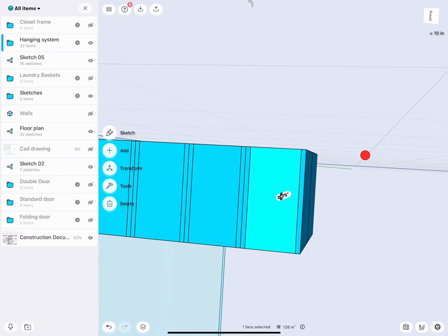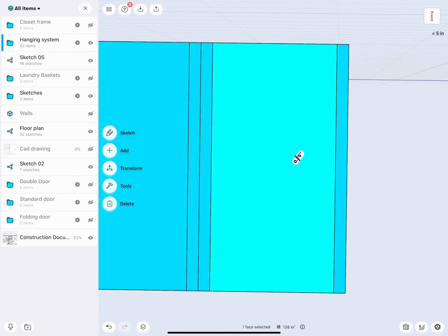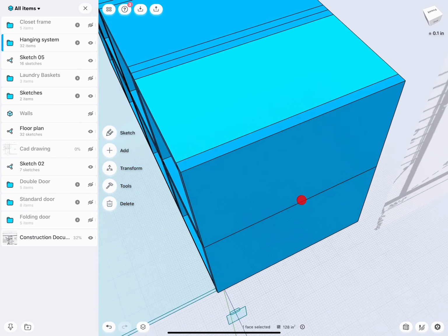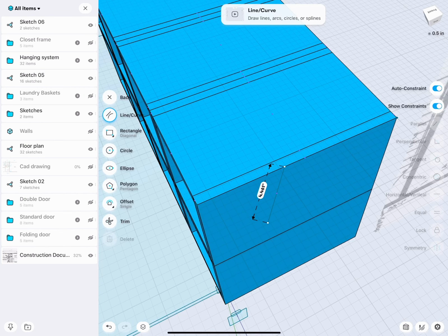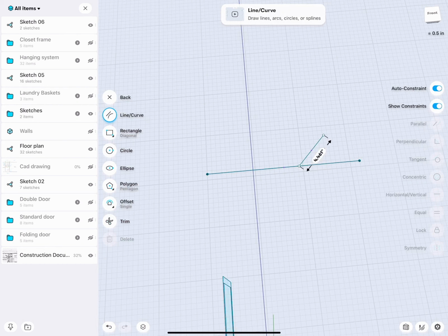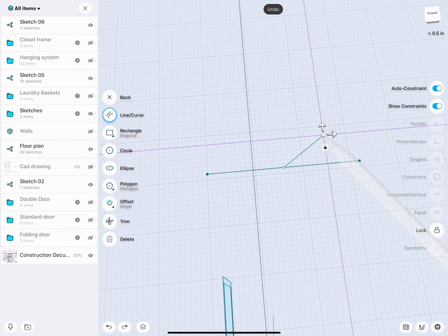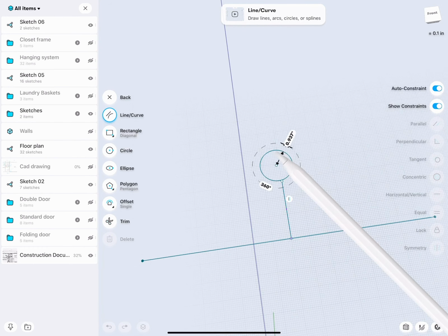I could select this side because I would like, obviously, the rod that's on top to be centered so it does not hang down rotated. So I can select this side with a finger now, double tap. So check this out. I will draw just somewhere a line and touch this edge, and then it will project this edge into a sketch. There I have a center point, or sorry, a midpoint. This I will make horizontal.